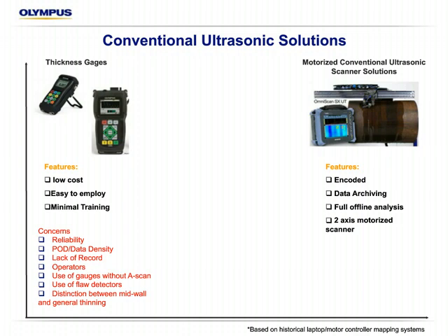In the last couple of years, a few of the flaw detectors do have some options that make them closer to the quality of a thickness gauge for thickness readings, but not quite as good as the best of the dedicated thickness gauges. So the real big hard call there, especially as I mentioned before, is that if you don't have that waveform, it's really hard to make a distinction between a mid-wall defect versus general thinning or some other type of condition.